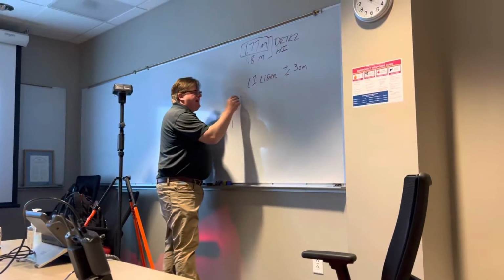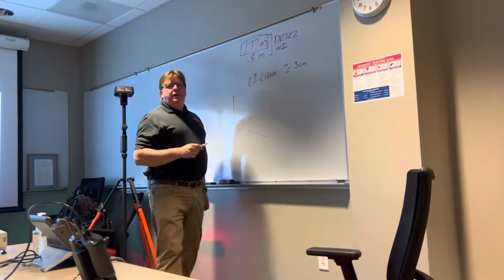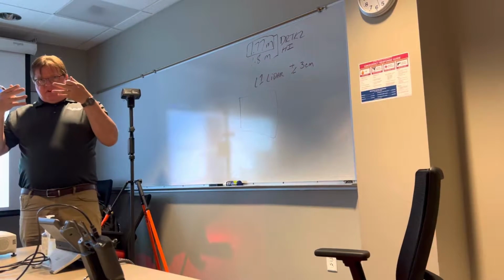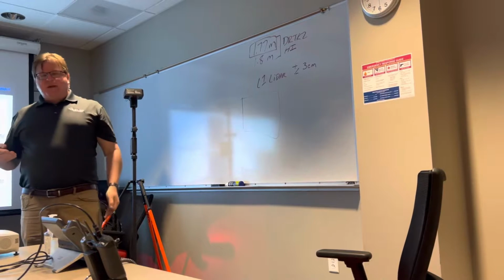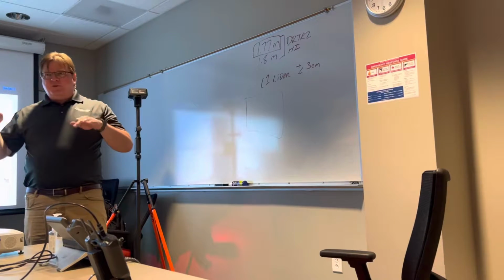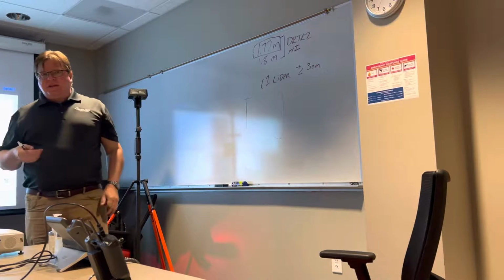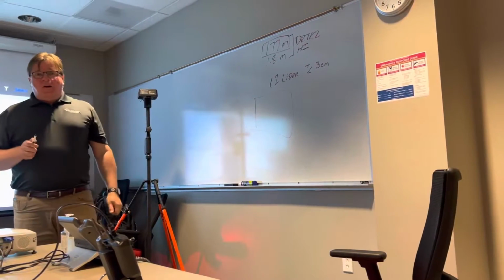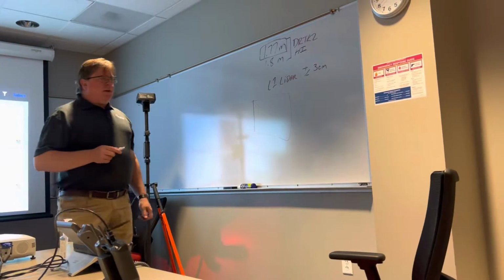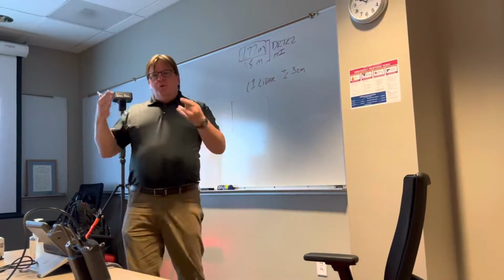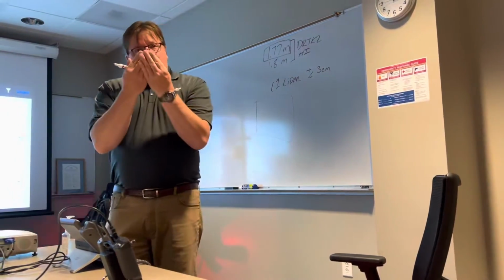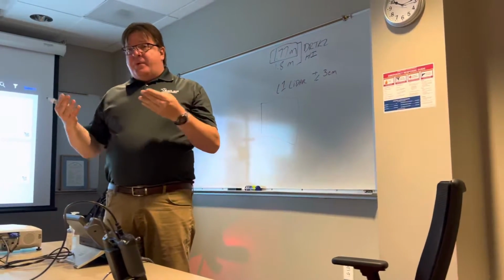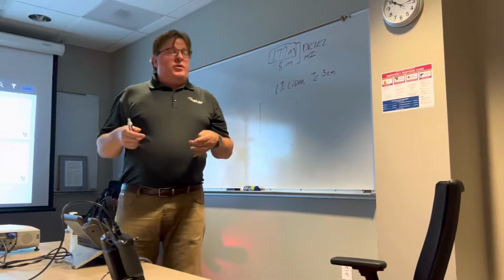If I have a site that I want to map, the way photogrammetry works, you guys are familiar with stereoscopic photos, or using aerial photographs with a binocular set to get that 3D. A ViewMaster. You ever played the ViewMaster? No? If you have two images that were taken a certain distance apart, it's like your eyes. You get binocular vision, and you can generate a 3D visual view from two photos.